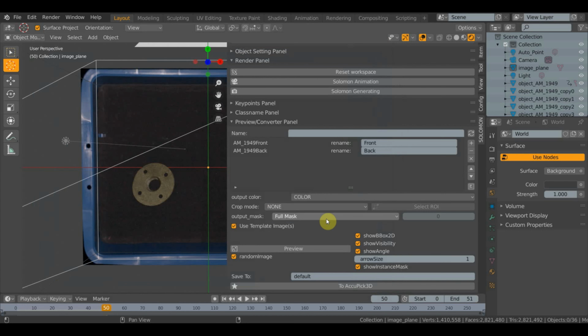You can decide the way you place the annotation over the object based on the configuration of the output mask function. By default, the option Full Mask is selected and it places the annotation considering the complete visible area of the object. If the object is divided into two or more parts, the option Biggest Area will calculate the largest visible area of the object and will place the annotation over it. Lastly, if the object is divided into two or more parts, the option Area Higher Than will consider the limit established by the user. The limit will be the minimum visible area required to place the annotation.